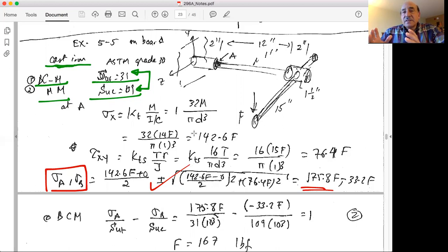So you have shear due to torsion. That's not the maximum shear, by the way. I think we talked about this in the midterm. So shear due to torsion, and you have an axial stress. You combine them in such a way that you get the maximum principal stresses sigma A and sigma B.